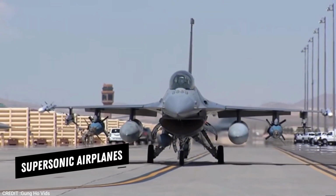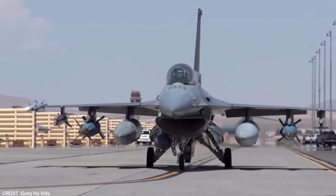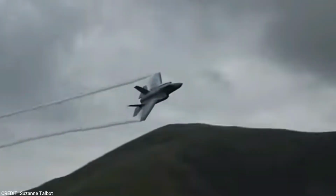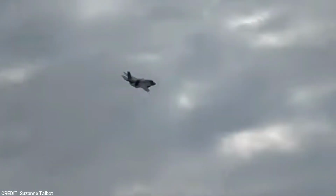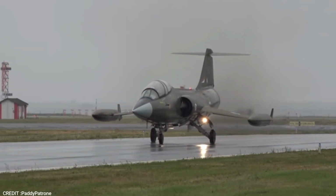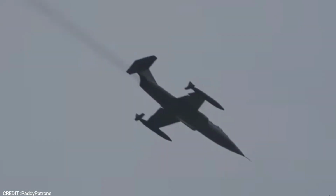For supersonic airplanes, the driving design feature was to reduce the strength of shock waves on the wings, and hence to reduce the supersonic wave drag. The thinner the airfoils, the weaker the shocks and the lower the wave drag. The Lockheed F-104, the first airplane to be designed for sustained speeds at Mach 2, is a perfect example.